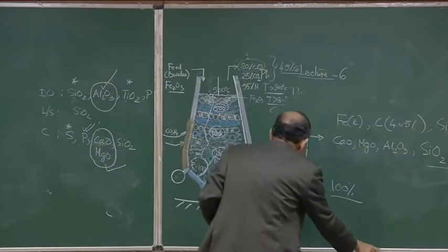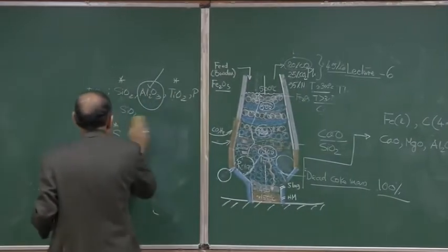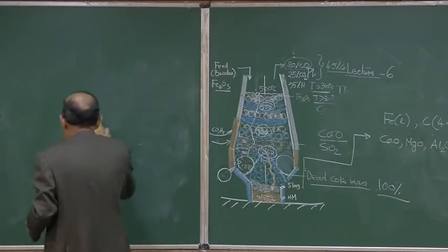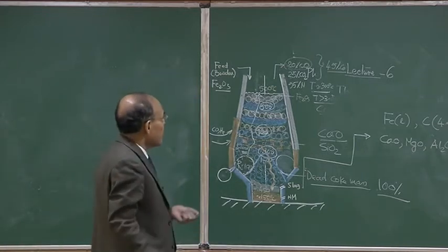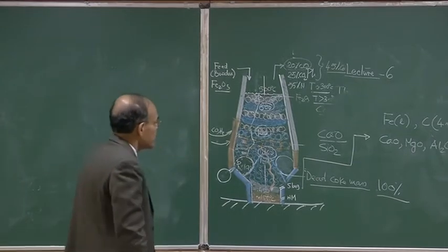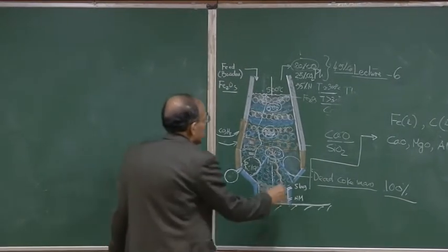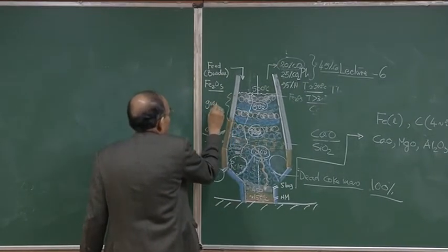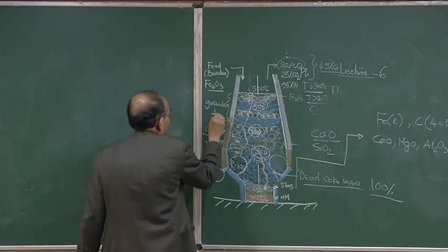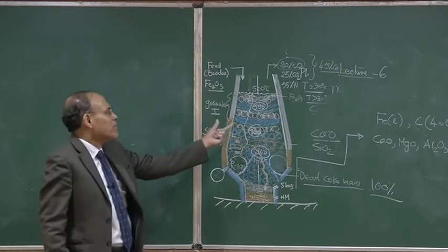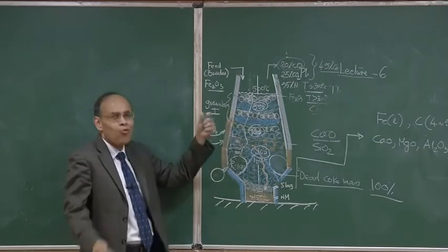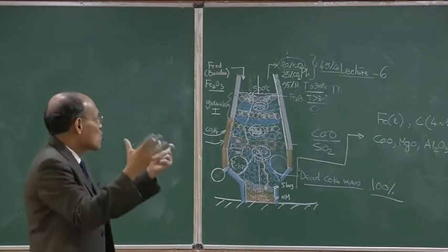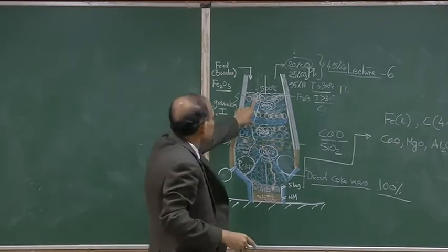Now, if you look at the blast furnace, people have dissected the blast furnace in pilot scale blast furnaces, and the blast furnaces are shown to be characterized into different regions, as I have tried to depict in a picture here. One such region is called the granular region, where mostly solid particles are there. The temperature is low, some reduction may have taken place, coke, lime and ore are all intact. So, granular particles, the solid particles maintaining their rigid shape, that is the region.